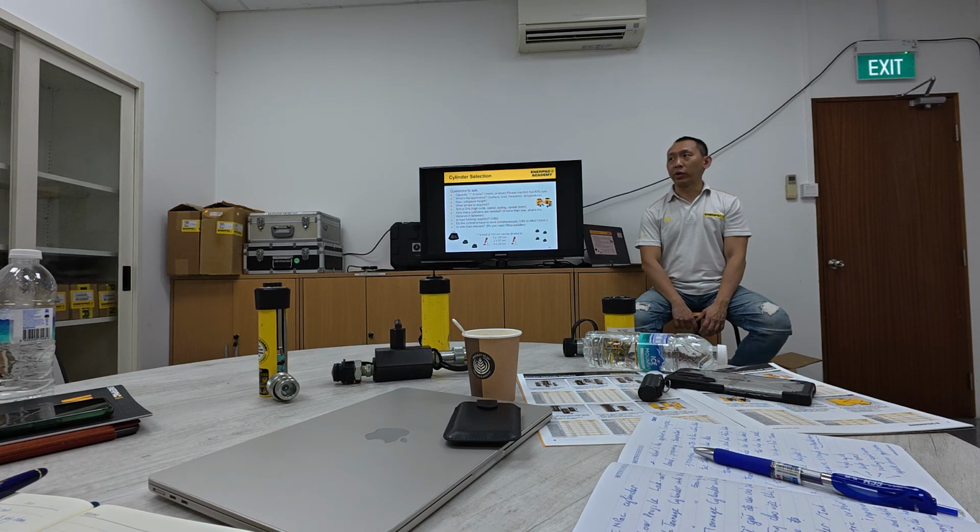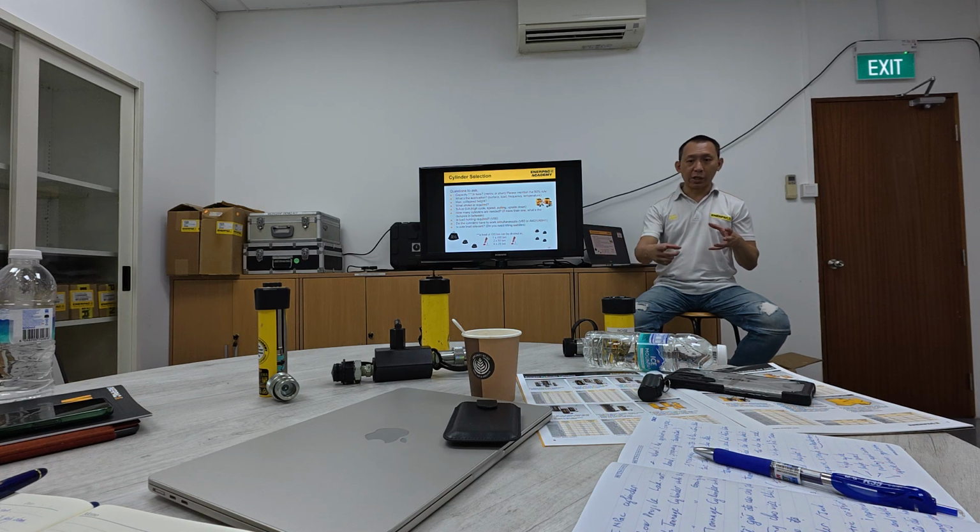Usually for that kind of application they also require the cylinder to be of certain dimensions. It cannot be so small. With low pressure the area is a lot bigger and the cylinder rod is a lot bigger, so the chance of cylinder failure is low. The tonnage of the cylinder is low, but the size is big and the rod is bigger, so it won't buckle.